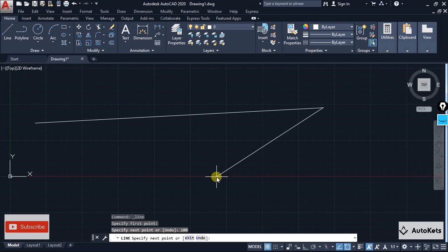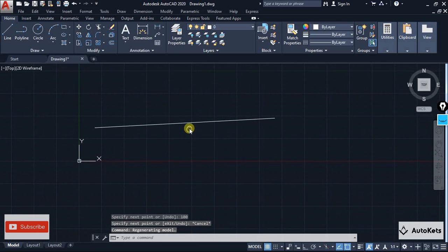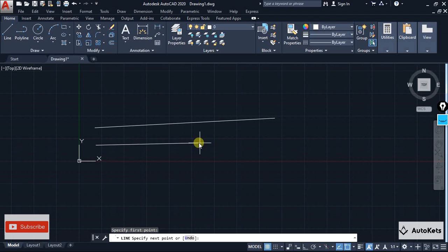So over here you can see that now the length is proper. This is 100 mm. Now let's say that we want to create a length of 50 mm. So I'm going to click anywhere, and that will be taken as the starting point. Locate your mouse where you want the line direction. So I want it again in this direction, so I'm going to place my mouse. I am not clicking any button of the mouse, and I'm going to type the 50 length over here. Write a 50 in the command box.